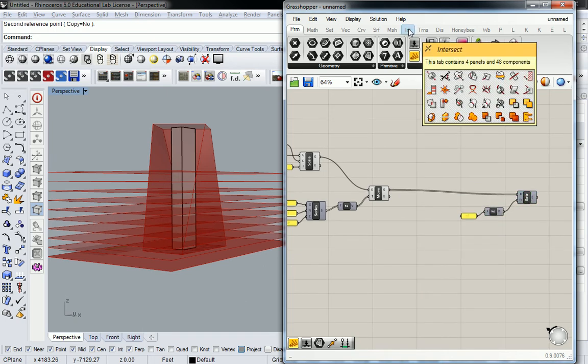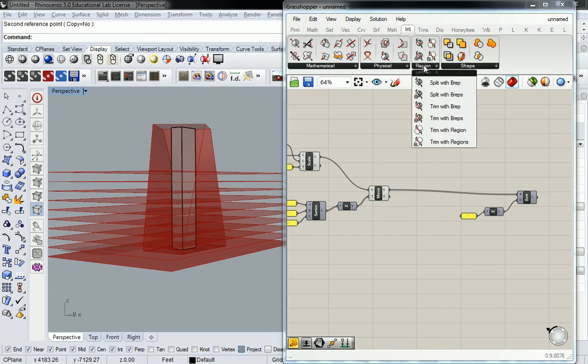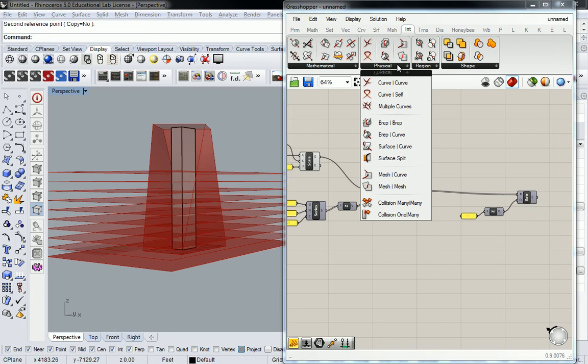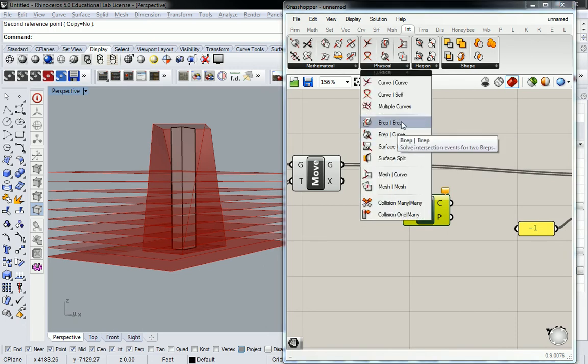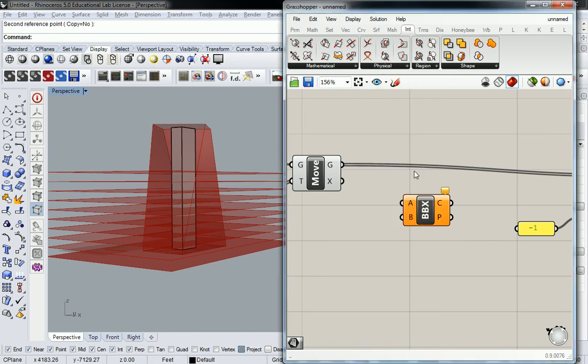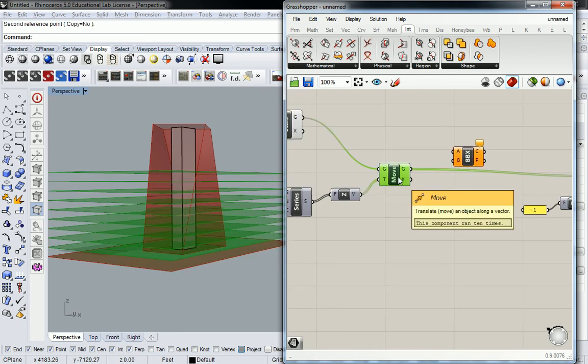Trim is going to act a little bit funny, but I'm going to go to intersect, and let's see, Brep. Yeah, Brep might do it, but we probably want surface. Yeah, Brep should do it because that's a surface. Yeah. Okay. So let's take Brep. It's this one right here. I think it will consider the surface to be a Brep in this case, but it doesn't always. So we're gonna take these here, and we have to trim it using another Brep, right?